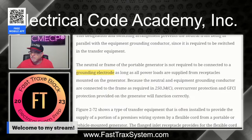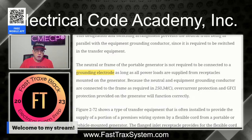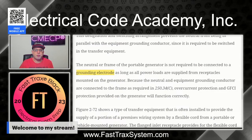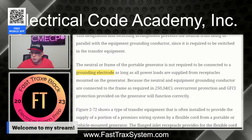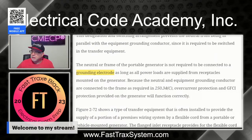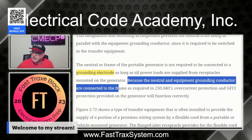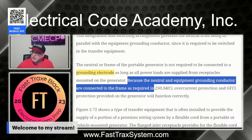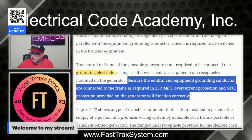We saw that. That was the very first thing that we looked at. Not required, if all the load is supplied through receptacles that are mounted on the generator, or the actual equipment associated with that generator is mounted on that actual generator. Now, because the neutral and equipment grounding conductor are connected to the frame, as required in 250.34(C), overcurrent protection and GFCI protection on the generator will function correctly.